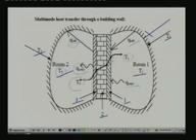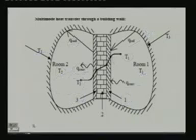Normally we know these two temperatures, and we also know the properties. For example, let us say that we know the properties of the walls 1, 2, 3, that means thermal conductivity, lengths, areas, etc. And for the time being, let us say that we know the heat transfer coefficient here, the heat transfer coefficient here, and the radiative heat transfer here and here. So the basic objective here is to calculate the heat transfer rate from this room to the other room.